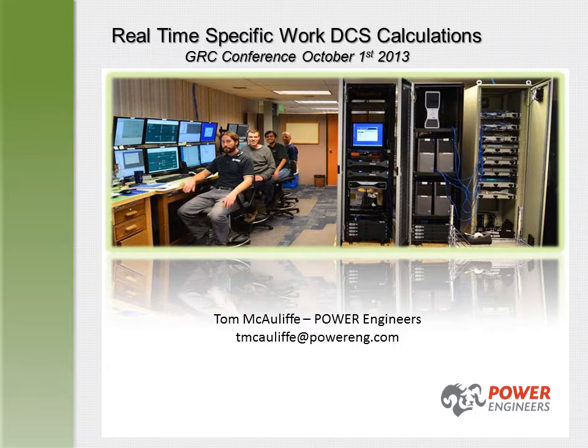The title of this paper is Real-Time Specific Work DCS Calculations, but it also describes implementing real-time calculations for turbine efficiency, reservoir enthalpy, separator and turbine exhaust steam quality, and the sensitivity of power output versus the condenser backpressure. The point is to maximize the value of your DCS by doing these sorts of calculations, historize the results for use by engineering and management, and present useful information in real time to your operators in order to give them the tools to improve your plant's performance.